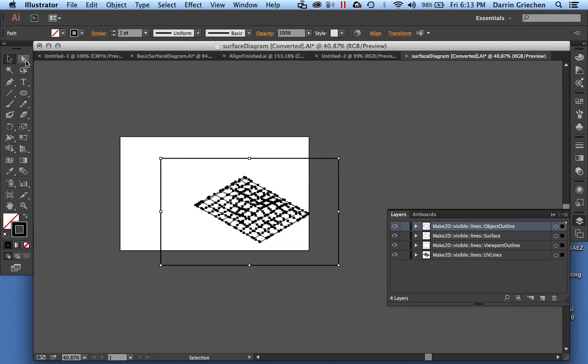So a vector is composed of lines and anchor points and handles. That's what all these little dots are, anchor points. By using the direct selection tool, we can select these individual anchor points. If we're using just the regular selection tool, it's just going to grab the whole line and all of the selection points. One of the things that's nice is that if we select the direct selection tool, you see that everything is still selected because we had it selected before.